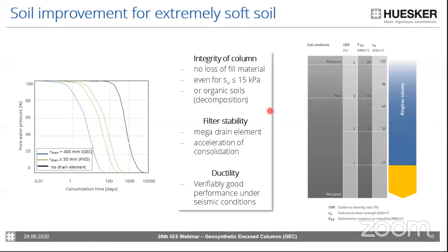as even for peaty soils, which will decompose over the service life of your structure, and where the lateral support will be lost, the fill material is still nicely protected in the encasement. And the encasement, or this geosynthetic sleeve, also helps as a mega drain element.